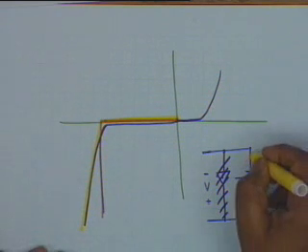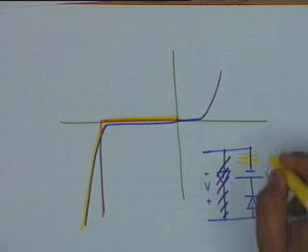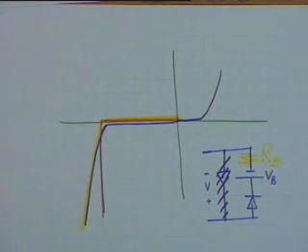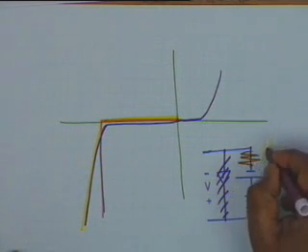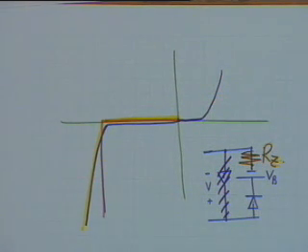All that you have to do is to include a resistance here, you call this RZ, the dynamic resistance of the Zener diode. Can you see the yellow color? No. All right. This is RZ, and this is a fairly good representation of a Zener diode.